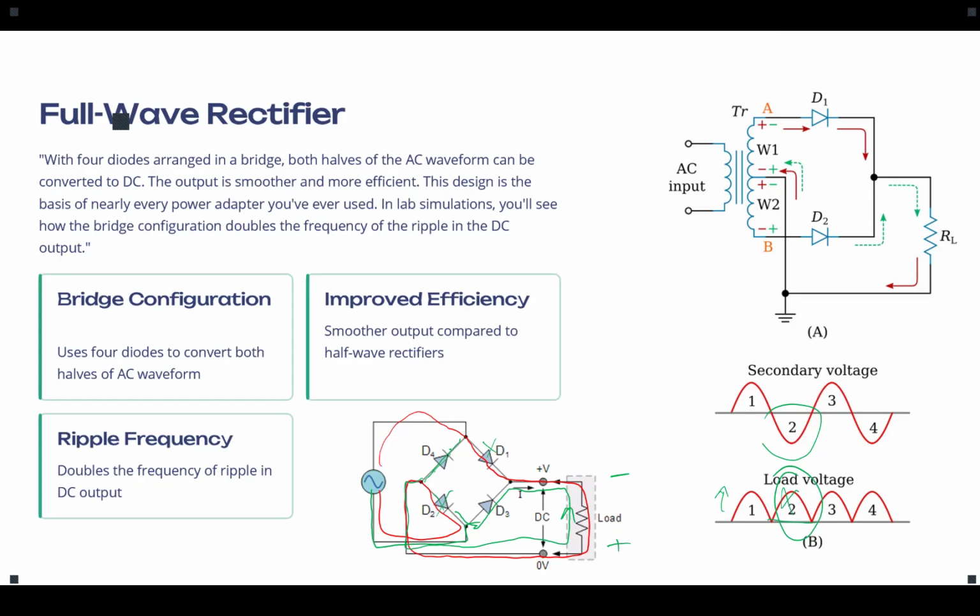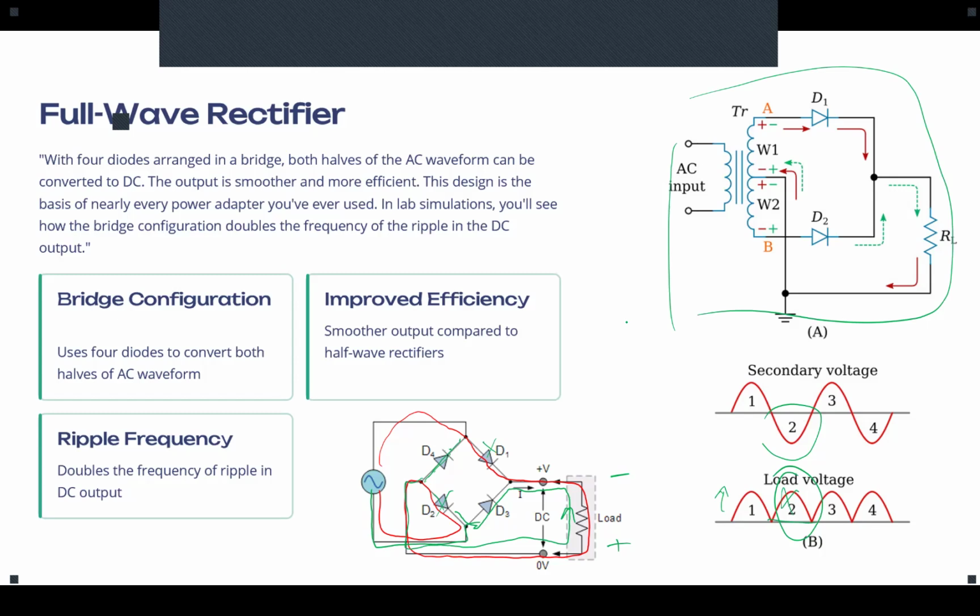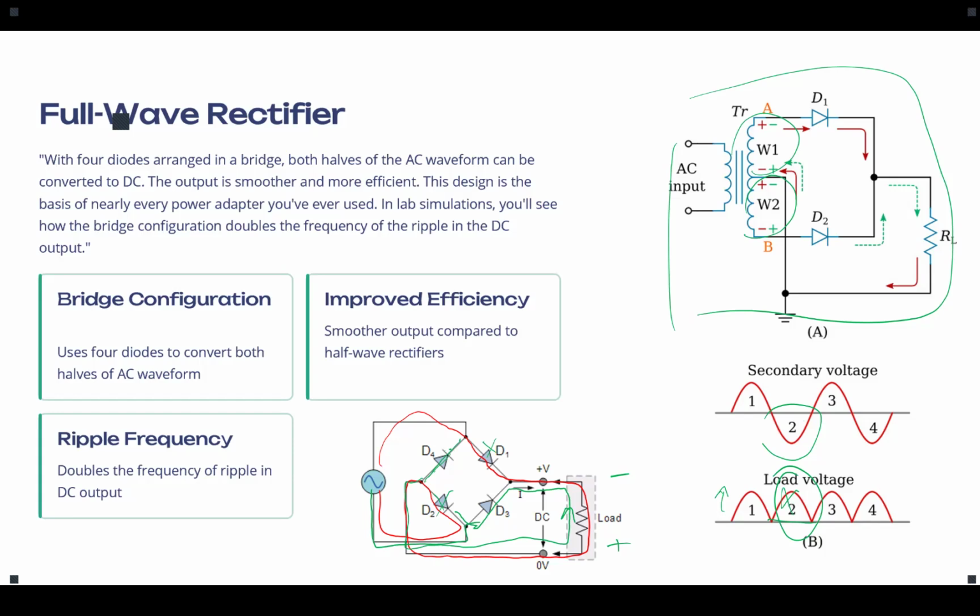Now, there is another type of rectifier. It works the same. As you can see, the graph shows the direction of the current. Be careful, there is a point. Look at the polarities. These two secondary windings have different direction, different polarity, so they basically change the direction of the voltage. Now, I want to ask a question. Both of them work as a full-wave rectifier, okay? But there is an advantage when you use a transformer instead of directly connecting the source.